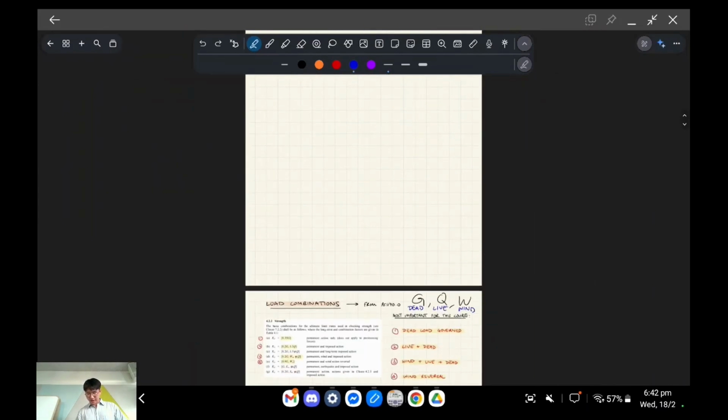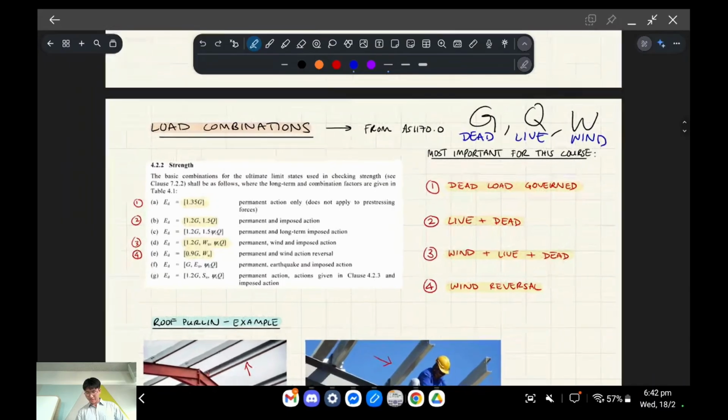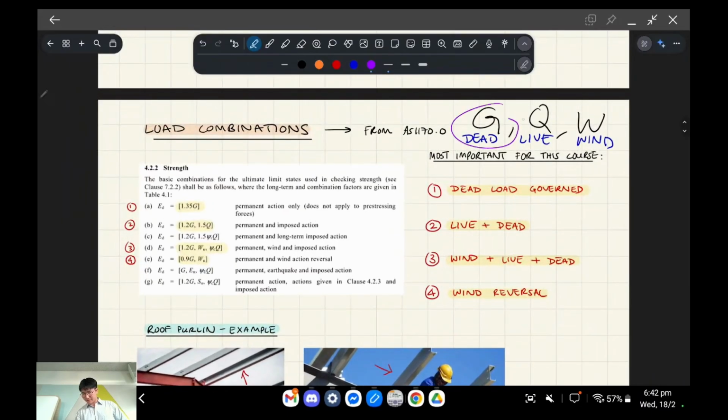But it's all described by these load combinations. So those are the different types of loads that will be factored. In a question, they'll usually give you the unfactored loads. Unfactored means we haven't applied the 20% increase in this load combination or whatever, right? They'll give you the unfactored loads, and then you have to factor them yourself.